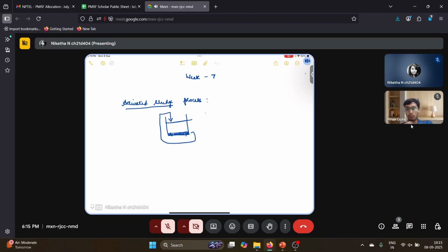The sludge contains a high concentration of living bacteria or living microorganisms as well, because once the population exceeds, along with the dead microbes, even live microbes will be present in the sludge. These live microbes can repopulate the tank when a fresh batch of wastewater enters it. When that wastewater batch does not have enough microbes, this sludge can be used to repopulate it.